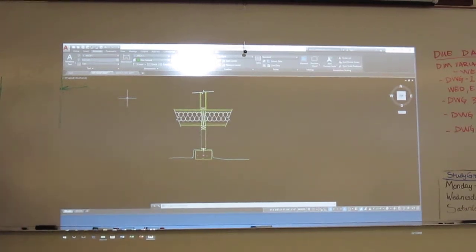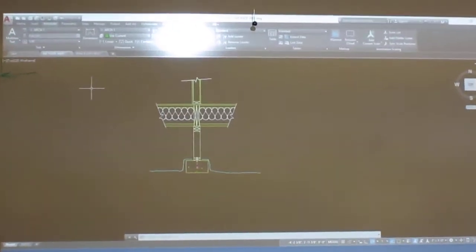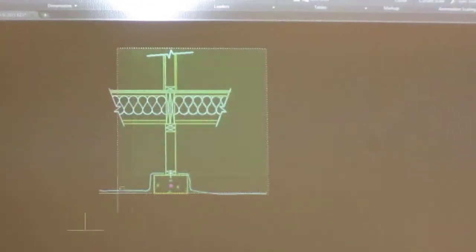So this one, if you look at it, you've got a series of blocks, which I don't even have in here because I've deleted them all out. Now, if you go to paper space on this, you're gonna find there's no title block in here either. This thing's never gonna be printed by itself, so we want to strip it down so when we XREF it in, we're not dealing with a whole bunch of layers and things like that. So all I want is my geometry.